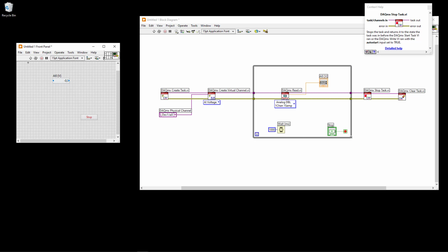So let's just run the application now. Now it shows 0, and then I connect my used 1.5 voltage battery, and then hopefully it should show the same value as in previous examples, namely 1.3 voltage, like this. This is more or less our final application, where we have used low-level DAQmx functions in order to configure and communicate and read data from our DAQ device.